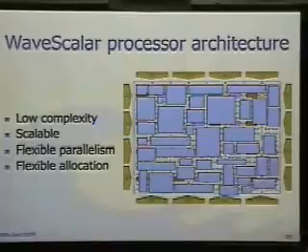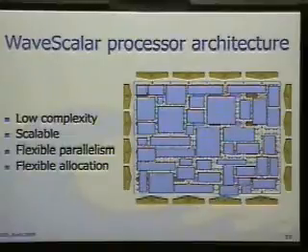So it sounds like the flip side of that is that any given thread, any given instruction only has one place in the entire processor where it can live, so you really have a one-way associative instruction cache. Oh. Right. So it's more like a 64-way instruction cache, or 64-way set associative iCache.